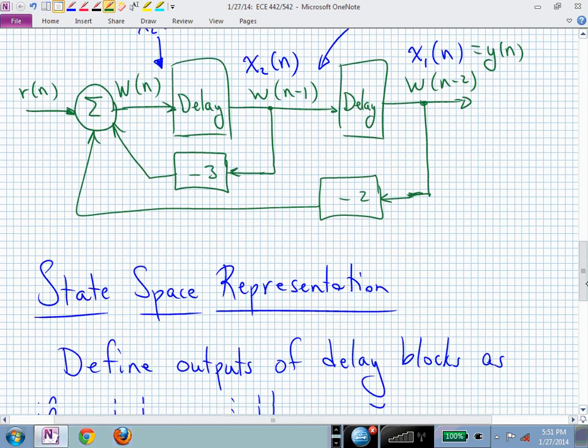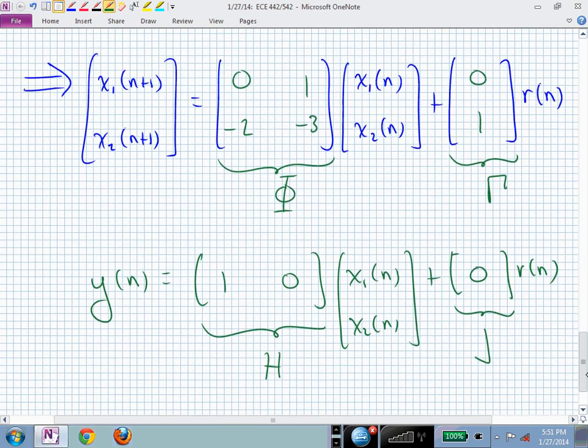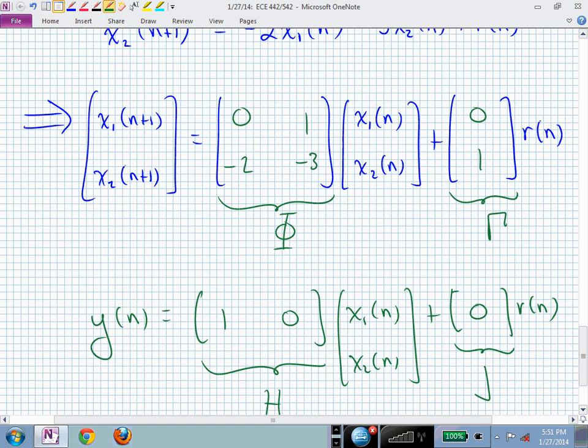If we wanted to find the dynamic behavior of this system in the open loop, it's represented by this system matrix phi. And we might be interested in the eigenvalues of that. That's actually going to be the poles of our system in our transfer function, so that we can connect to all these concepts from linear algebra.